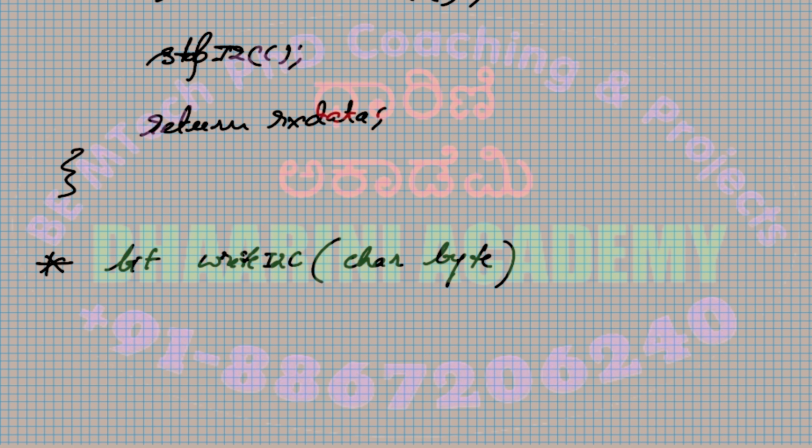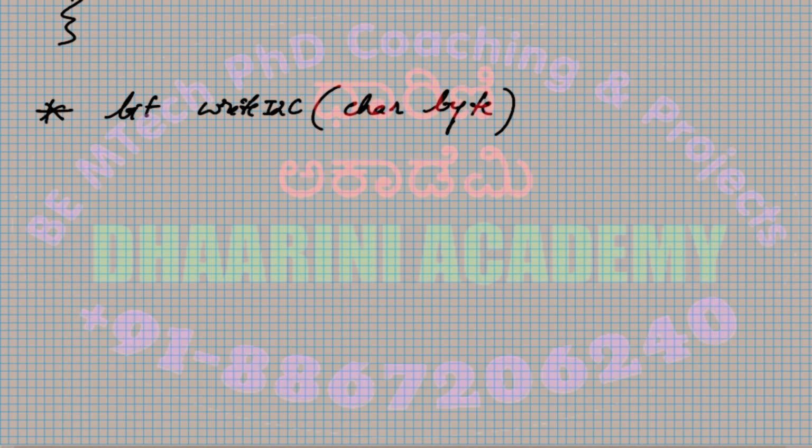Okay, now we'll come to the actual function which is used to write the I2C. It writes a data and it returns saying that yes, writing is done or not, because after you send a data there is an acknowledgement bit coming from the slave, right? So that is what I am returning here. Whether it is successful or not, I will come to know after this. Correct.